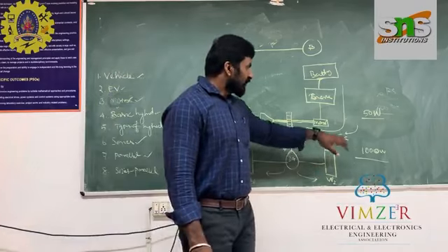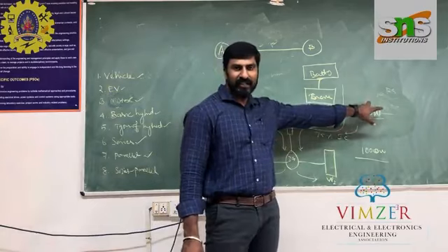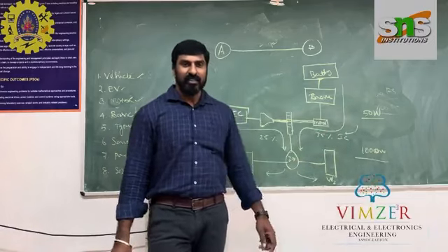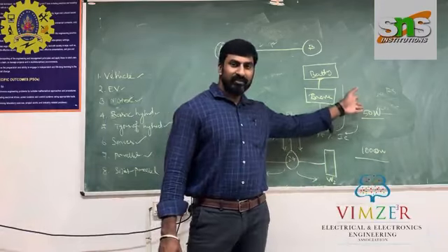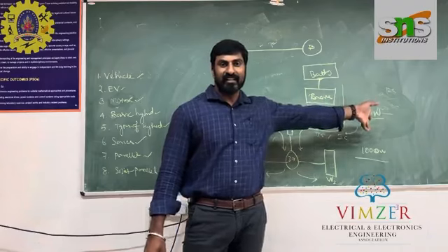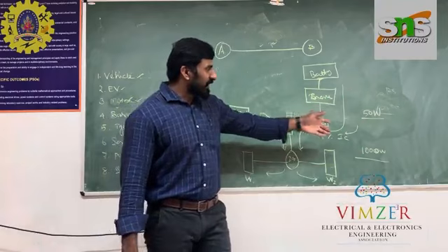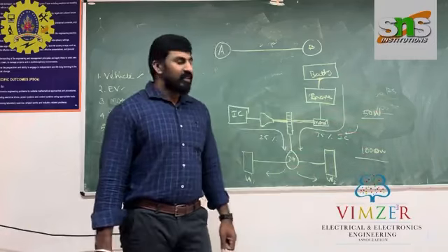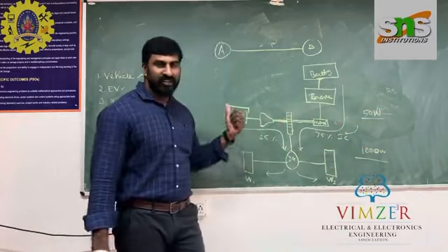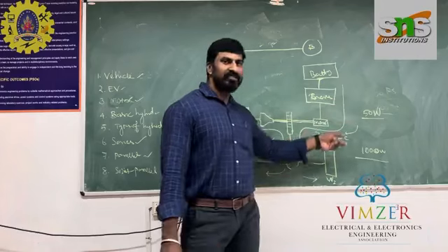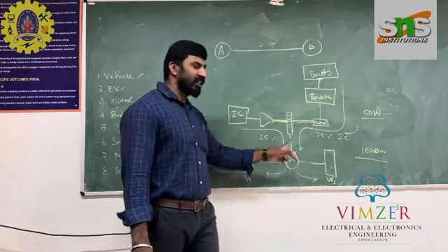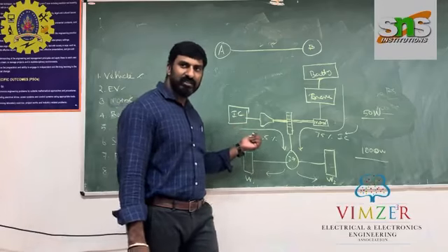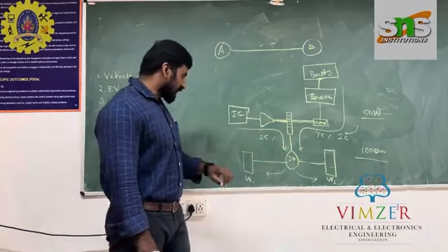So in that condition, if we design a battery for the full rating to run the vehicle, it will be a higher capital cost, because the vehicle does not need to have that full capacity of power delivery from the battery. So we can design a smaller battery. We can cut our battery cost and our construction costs. That's why we are using these 2 different kinds of sources. One source always runs with the help of the battery, motor, and vehicle, and the other supports whenever we need it, the internal combustion engine system. This is called a parallel hybrid system.